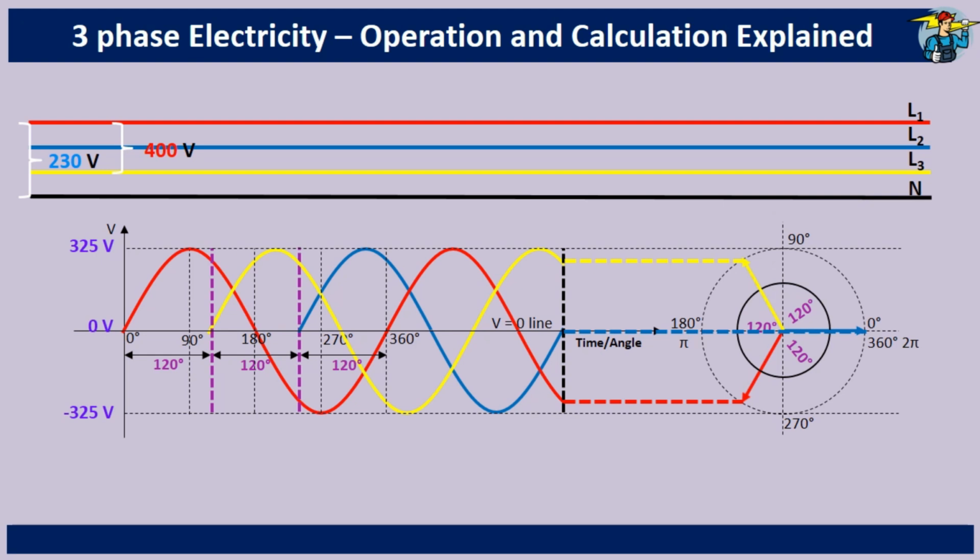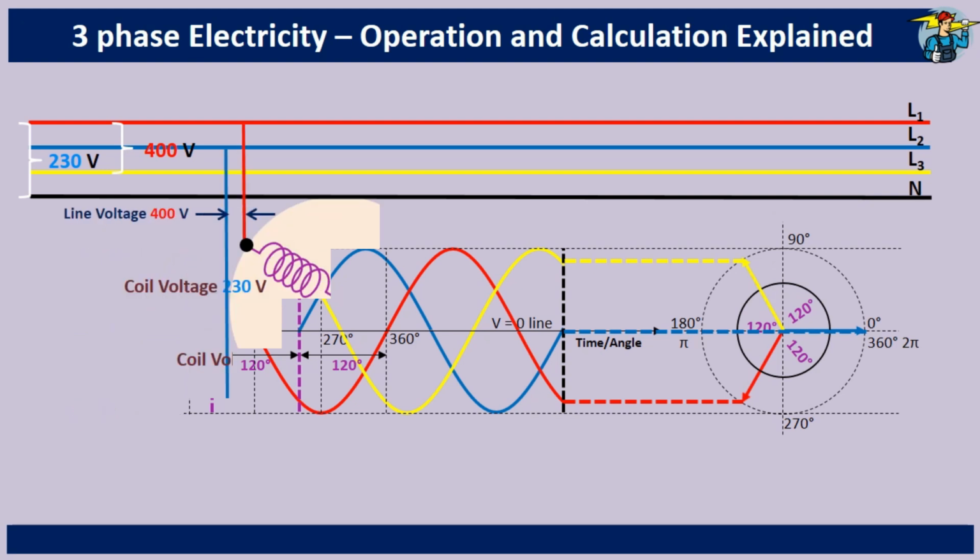When a three-phase induction motor, or any other balanced three-phase load is connected, the current on each of the three lines behaves in the same way as the voltage. As a result, the total current flowing through the three lines is also zero, meaning no current flows through the neutral wire in a balanced system.